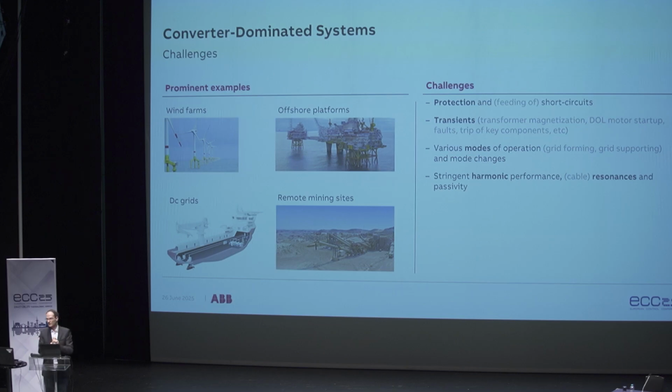And one interesting one is passivity. So a converter should not react to harmonics it sees, it should ignore them. And in order to get passivity, you probably want to have as high a bandwidth as possible. So you want to not have a negative phase when you pick up that harmonic, because then you start amplifying it. If your phase is close to zero, you will not amplify it, you would rather ignore it. So passivity you can typically achieve by having ultimate bandwidth.